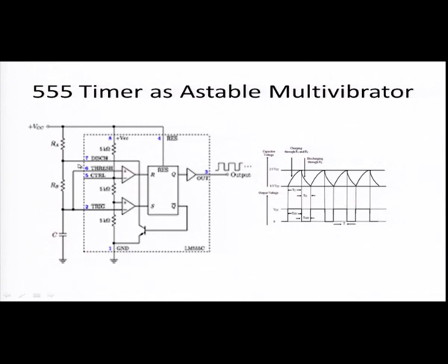So, if it is connected, then this transistor is going to produce the discharge path for the capacitor. Once it is connected in the circuit, the capacitor's voltage will get discharged through this RB and this transistor Q2. Say this is Q1 and the reset transistor will be called Q2. If Q bar is high, then the transistor is connected in the circuit. Now, the capacitor is discharged towards ground potential through RB, and once it is discharged to 0, the output